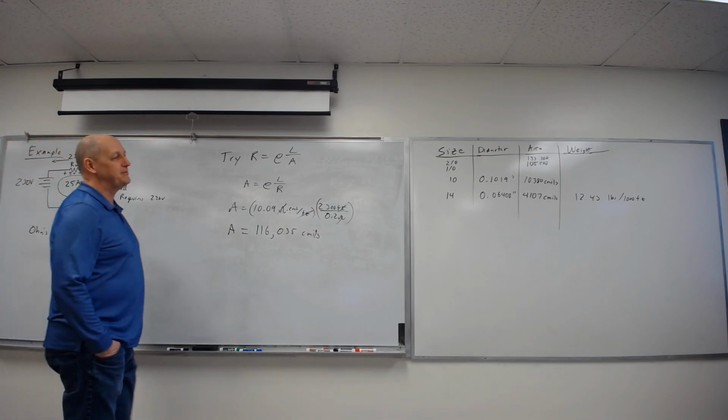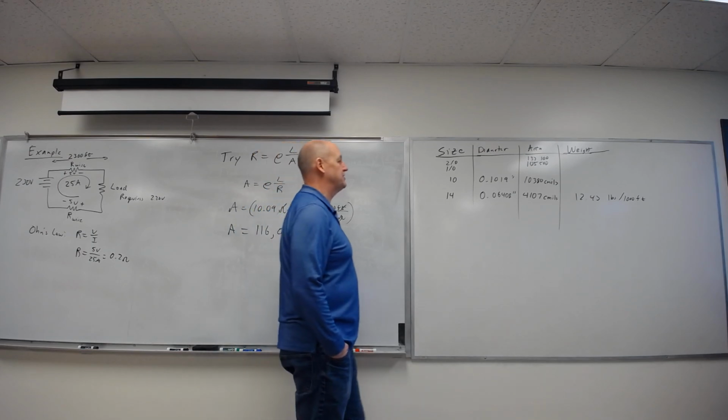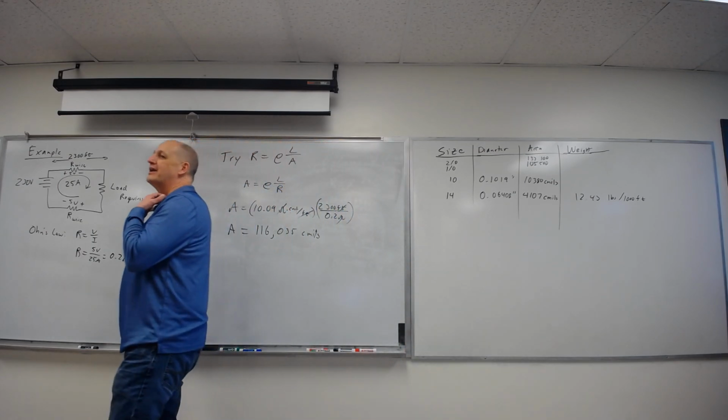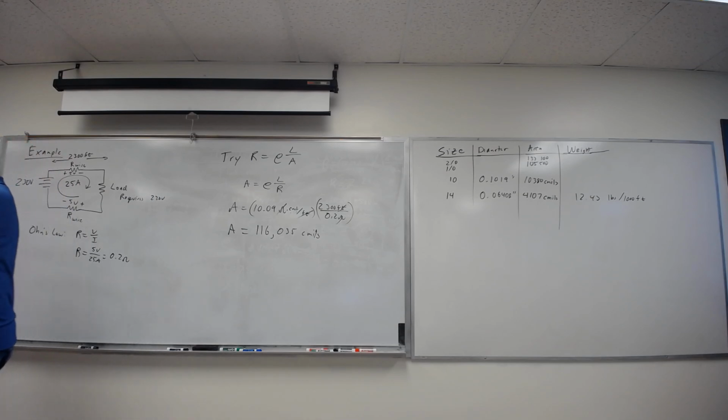Aluminum has a conductivity that's almost as good as copper. In fact, we used it for wiring houses for a while. We had a lot of aluminum around and not so much copper. And the biggest issue with it is when it overheats, it catches other things on fire, whereas copper tends to overheat without that problem. And when the two come together, they actually have a weird corrosion. So there's a certain method you have to go through to connect them. So we don't use it much anymore.